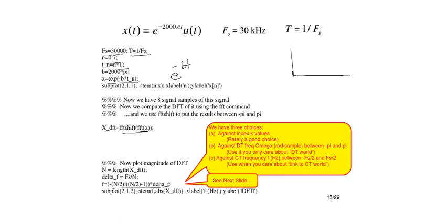When you want to convert to hertz, you have to find out how many frequency coefficients correspond to 1 hertz. So essentially you have to compute delta f, where delta f is nothing but the sampling frequency divided by the number of FFT points. Since we are sampling at 30 megahertz and doing an 8 sample DFT, we have to divide this frequency axis by 8, right?